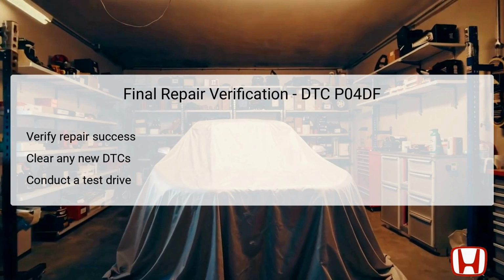After completing the necessary repairs and successfully passing the EVAP function test, a final repair verification is essential. Technicians should ensure to verify the success of the repair by checking if the P04DF code has cleared and no new diagnostic trouble codes have appeared. This step involves again using the Honda Diagnostic System HDS to scan for any stored codes and ensure that the vehicle's computer systems are functioning as expected.